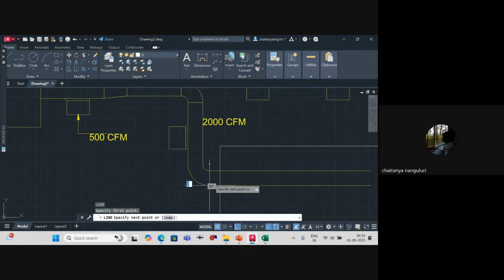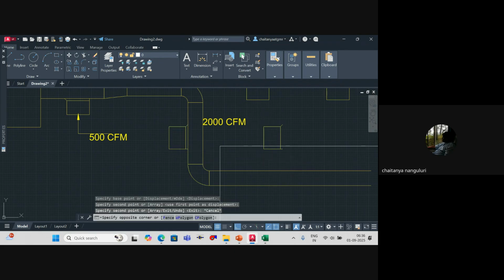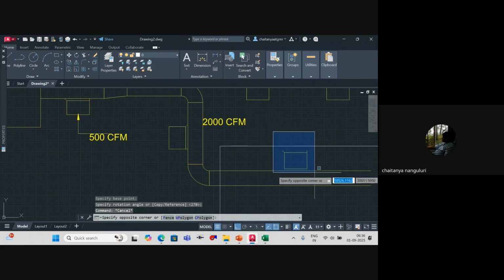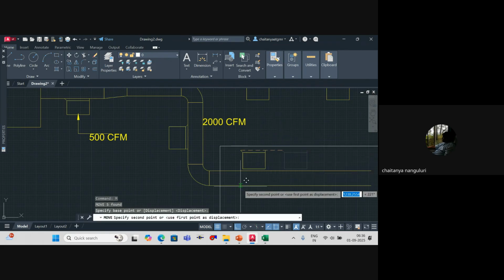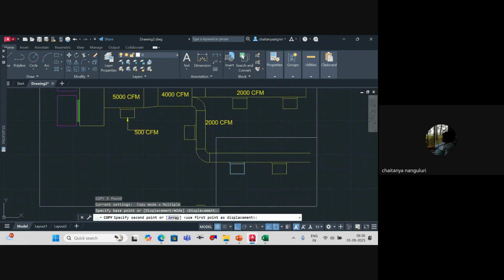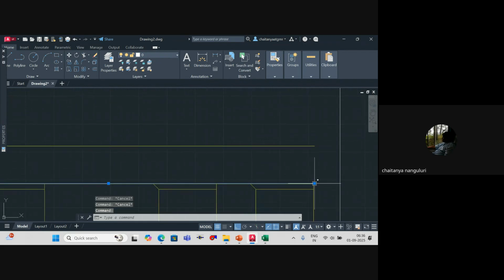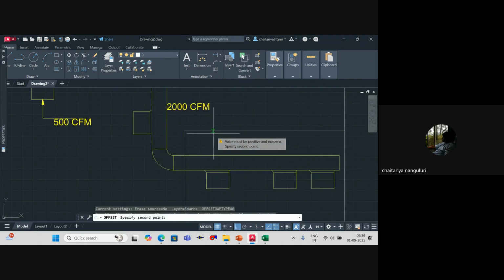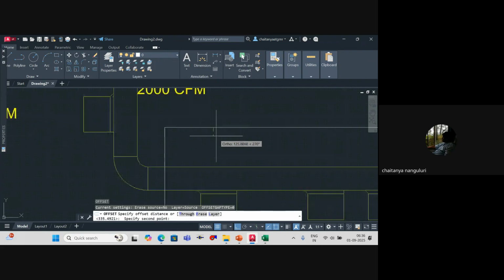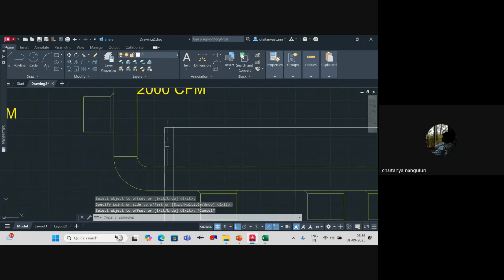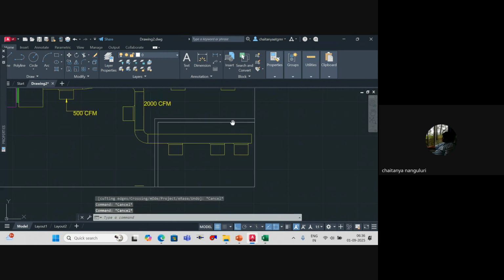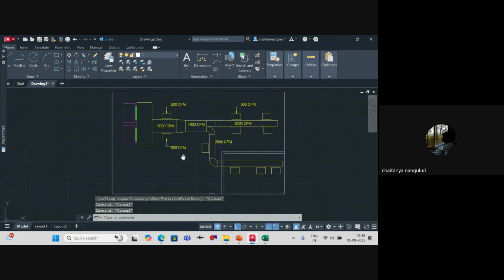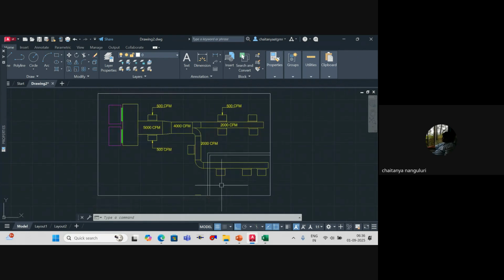So this duct you have used, this duct you have used. Now what will happen? Let's say this is the airflow rate you're going for. These are your collars that you have. But let's say this room is a critical room where you have to do isolation of the fire. This small rectangular room has a separate room wall, for which isolation is required. Let's say this is a battery room or a UPS room, or vice versa, whatever it is.